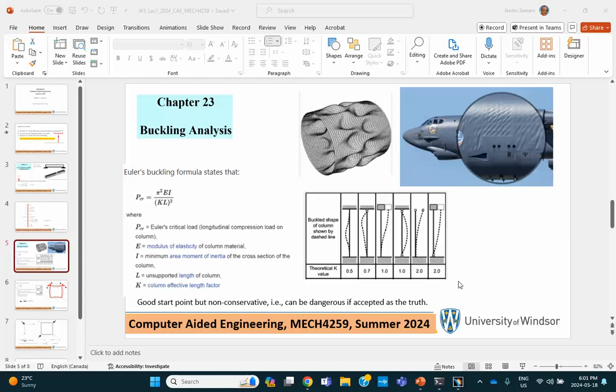But buckling occurs in three-dimensional geometries, and as you can see here, the fuselage of that aircraft has buckled. It doesn't mean it's going to fall out of the sky. It's just that, hopefully that buckling does not cause a permanent yield, permanent deformation, and when the plane lands or changes the condition of the flight, that buckling will not be dangerous.